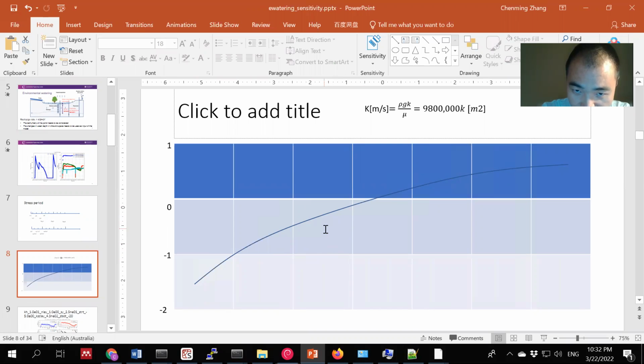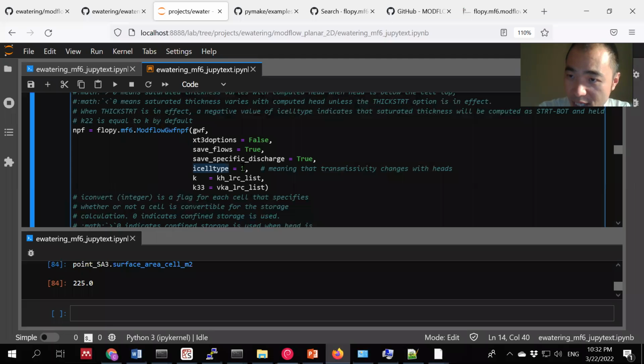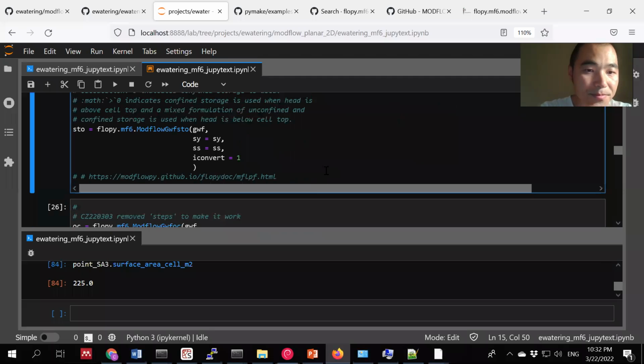So for this particular cell, the transmissivity is K times B, which is from here, where my cursor is, up to here. And these are subject to change, and the model actually considered that. So I enabled that so that if the cell is partially water inundated, the transmissivity will be changed. That's the function that we implemented in the model.